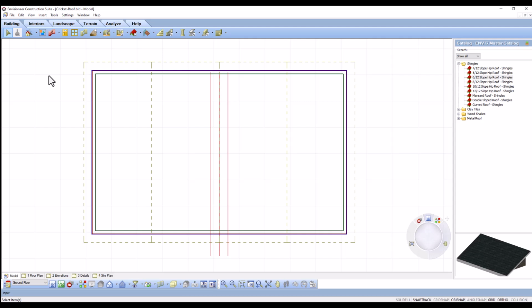In a roof design that needs adjusting to help facilitate the shedding of water and/or snow, a cricket will need to be created. In Envisioneer, we will create the cricket using surfaces and adding it to a parallel gable roof design. First, we need to know the height of the fascia board.